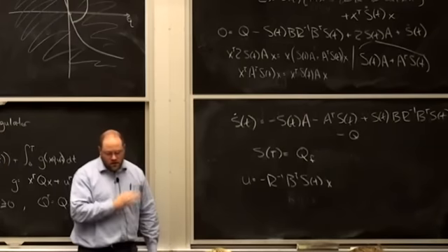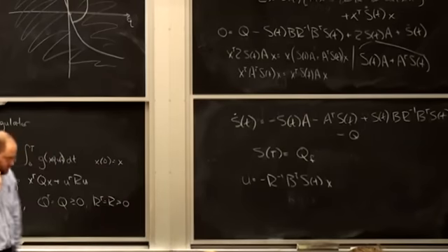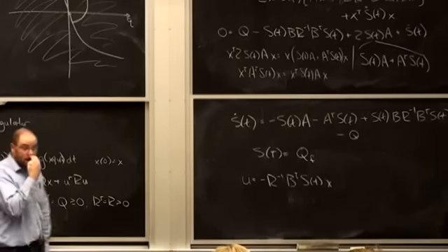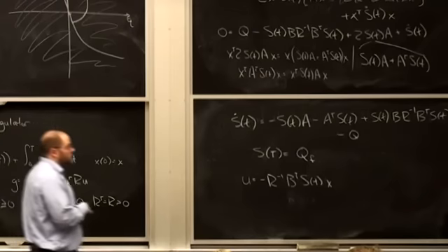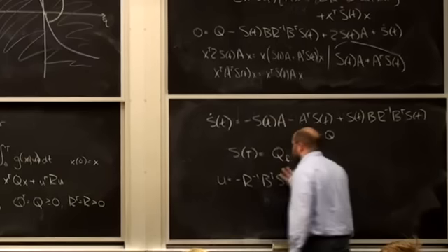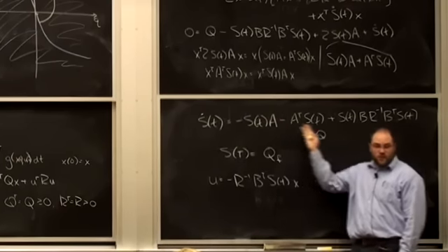So this is one of the absolute fundamental results in optimal control. If you want to know the infinite horizon solution, the solution as time goes to infinity, remember my cost function initially, for the problem we're trying to solve, was an infinite integral. It turns out that the infinite horizon solution is the steady state solution of this equation.